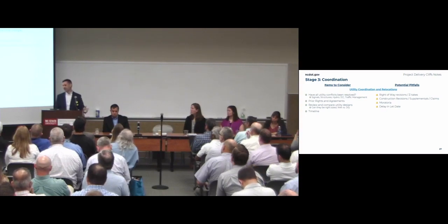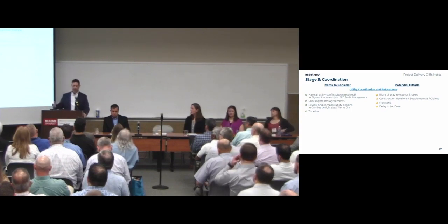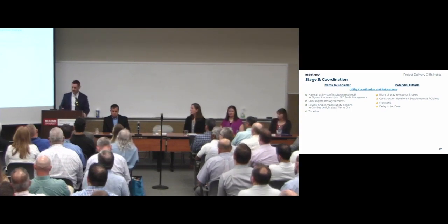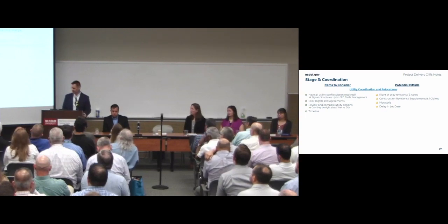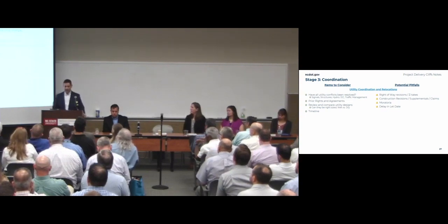When can we cut trees? When can we not? Well, we got to cut trees for Duke. If that delays them 6-8 months, we've delayed a let potentially 6 or 8 months or more. So we really need to be thinking about that in addition to the permitting. I mentioned permits before and making sure it accounts for utility relocations. We need to make sure we have those permits in hand before the utilities get started if they are affecting our permit. So keep that in mind.